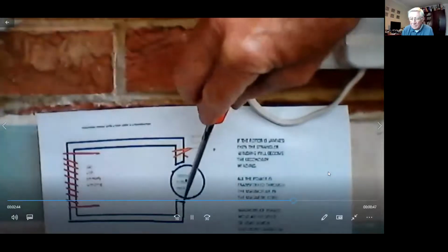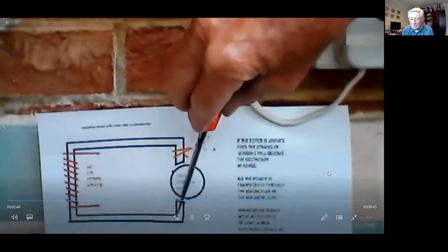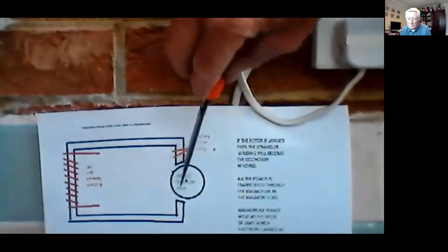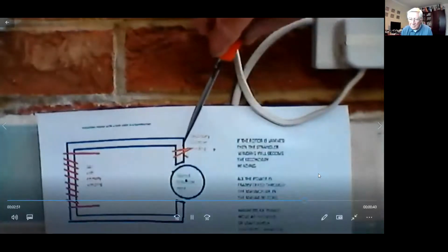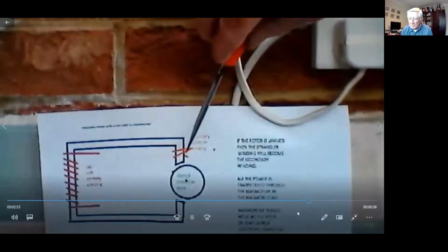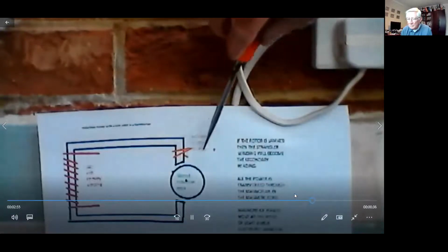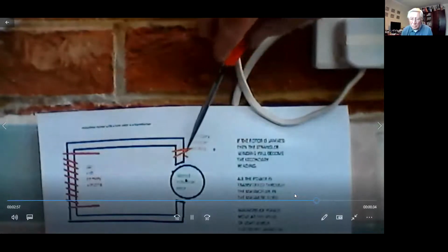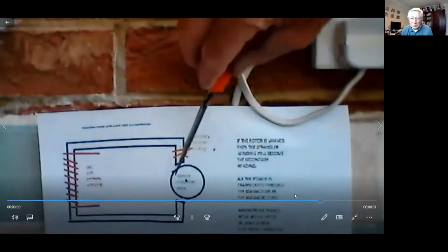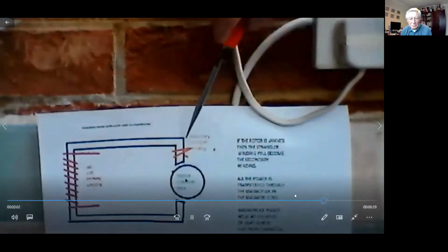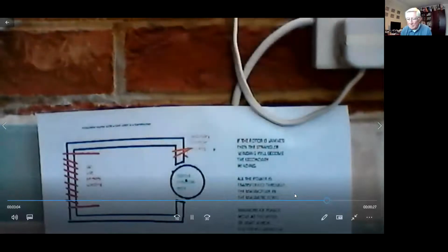And of course, once we jam that rotor, then that completed the magnetic path, and the only thing in the secondary then is the teaser winding, or the winding that is shading the pole. And of course, there's a big air gap there, which is stopping it from doing anything else.